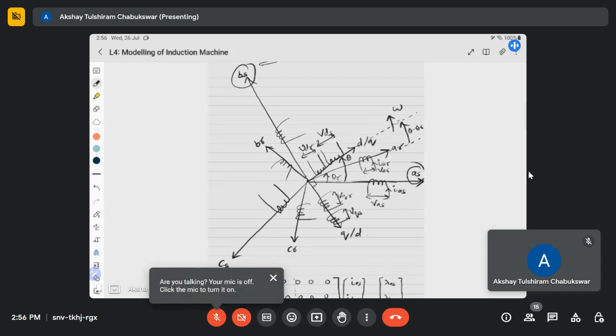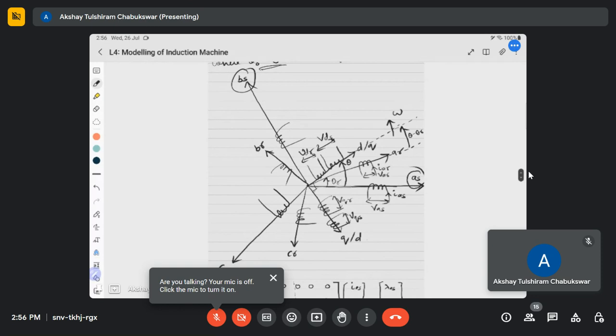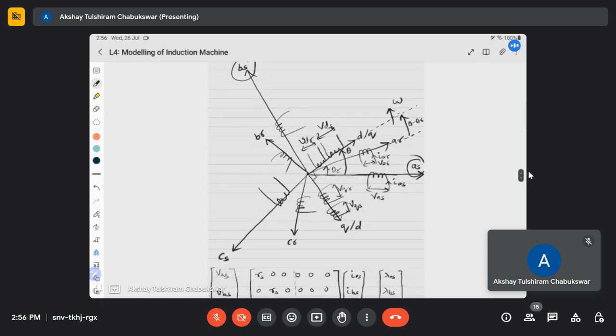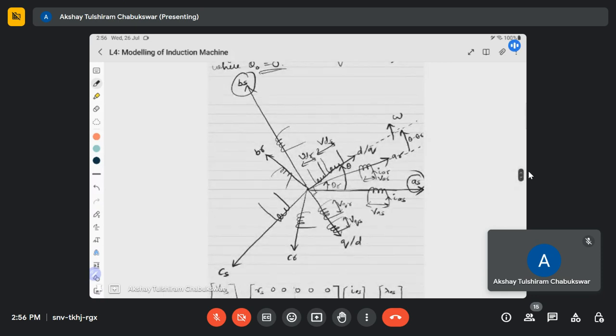based on that you can connect the motor. As we are exciting the motor, the stator conductors get this power supply, and as the conductors are placed in these distributed slots, and the electrical supply is sinusoidal, which is V sin omega t for A phase, V sin(omega t minus 2 pi by 3) for B phase, and V sin(omega t plus 2 pi by 3) for C phase, all the three quantities are sinusoidal in nature, and as the conductors are placed distributed in a circle, the resultant flux produced by the current flowing into the stator coils will be of rotating nature. So that flux vector will be rotating.